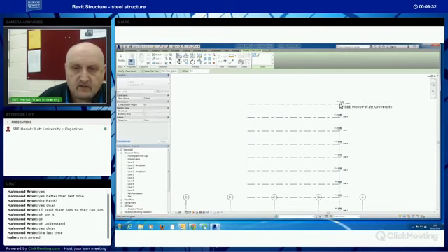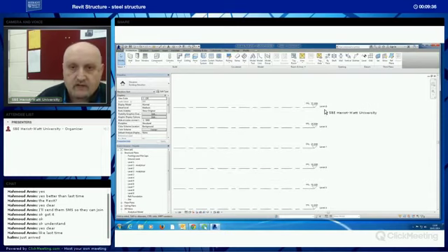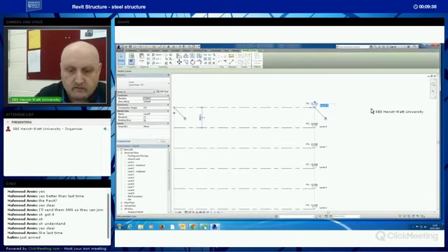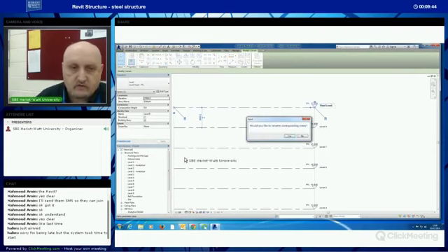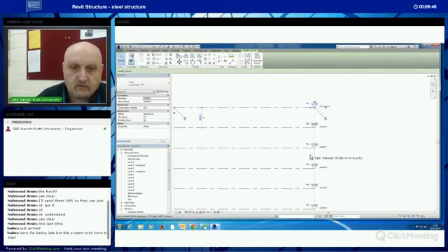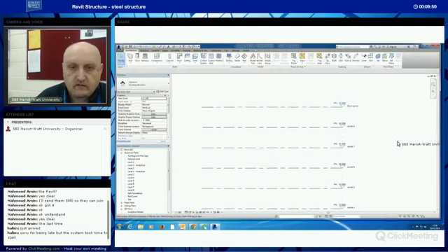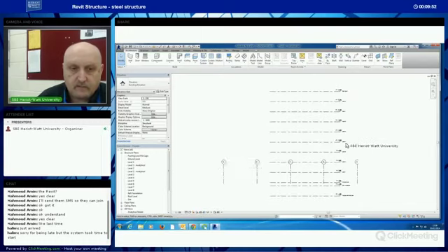So I'm thinking ahead a wee bit. And that's, I've gone up to level 9, that'll do. I'll call this one roof level. Click in the white space as usual. Same old question about level 9 in here, and that'll become a roof level. Okay? So that's the setup finished.